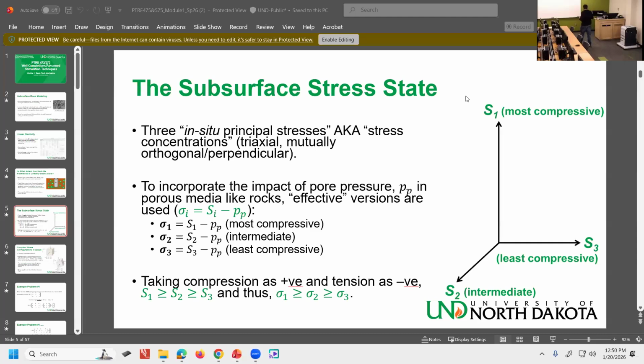So they still stay the same. And that is assuming a solid with static pore pressure. What I mean by static pore pressure is that the fluid in the pores is not moving. So I have pore pressure, I don't have poroelasticity. I don't have fluid movement in the pores. The pore size doesn't change, it stays as it is. No fluid is moving inside the pores. It just stays static. Okay, I modeled that by just subtracting pore pressure.